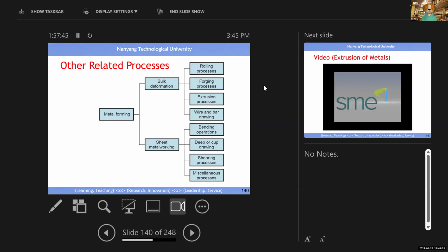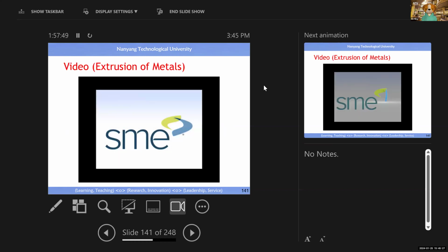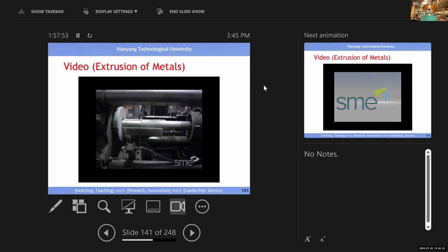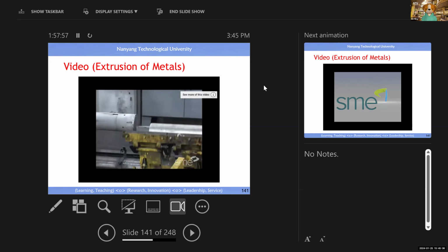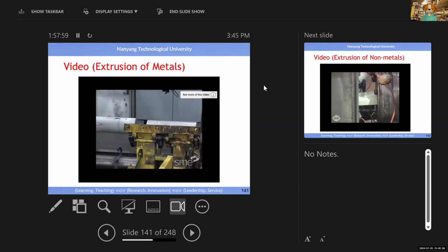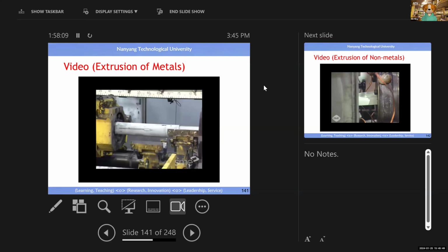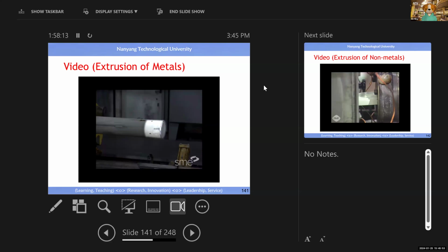Extrusion is also a very popular process in industry, right? The primary design of products. So it's the input, or forward extrusion. In direct extrusion, the hot billet is loaded into a thick wall container and forced through an extrusion die secured in a hole. The force for extruding is applied by a ram, along with an intermediate reusable dummy block.